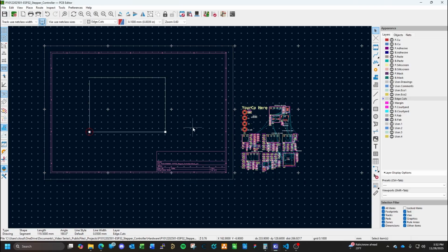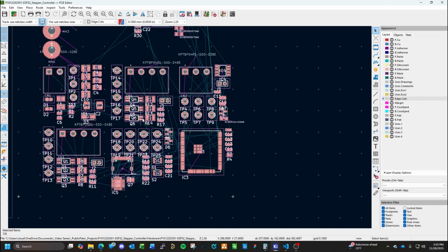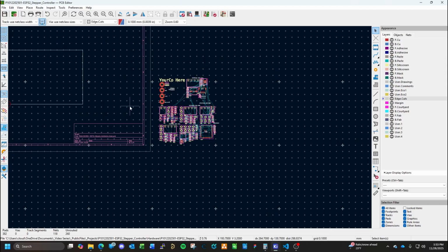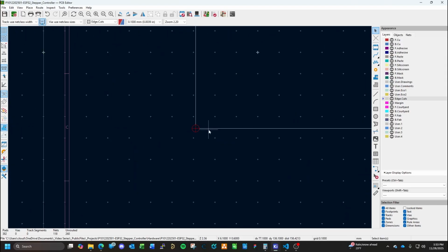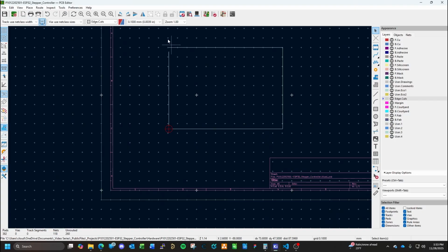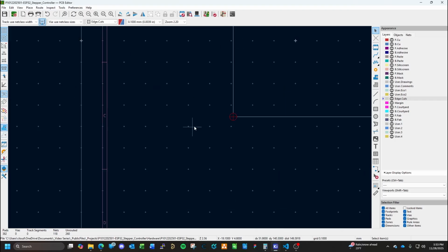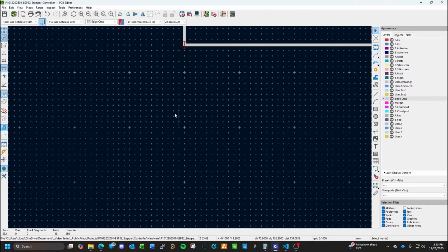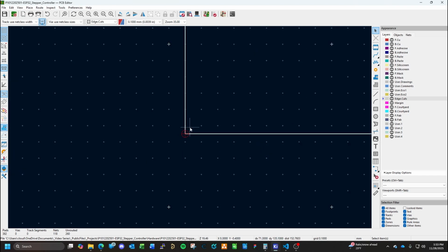So last time we left off, we just pretty much got everything pushed over to the PCB editor, the layout editor, KiCad. All the components are here in one big old cluster. All the footprints, that is. And I've been messing with things to reset an origin, set my snap to grid, everything. You could do dots or crosses. I kind of like the crosses, a little bit easier. Snapping to grid seemed to be really fine. You have to be zoomed in a little bit to snap to grid better, but that's fine.